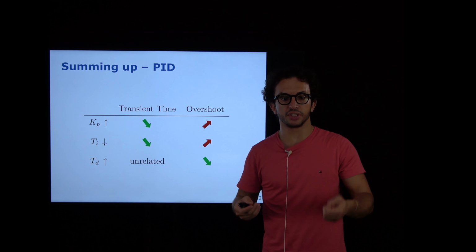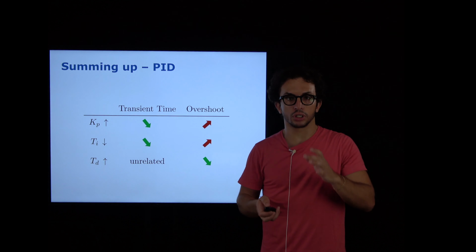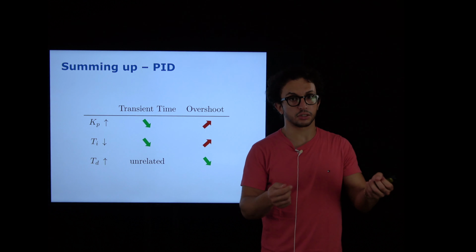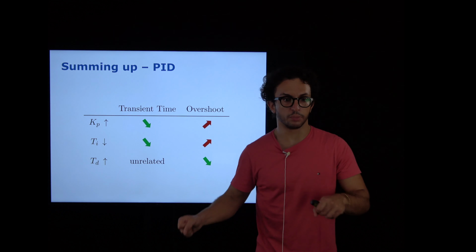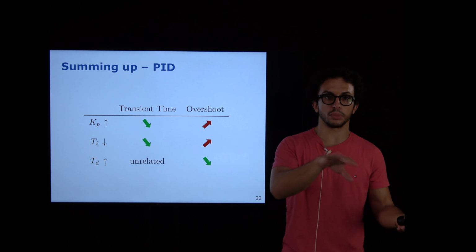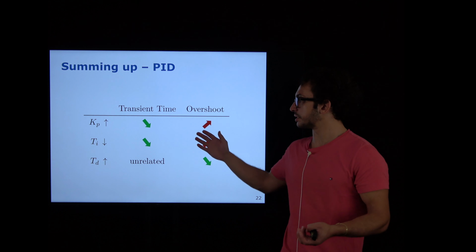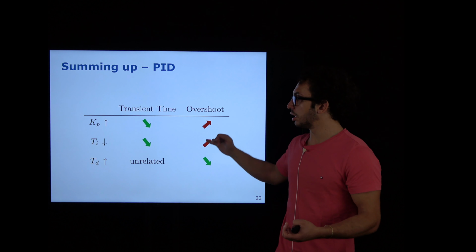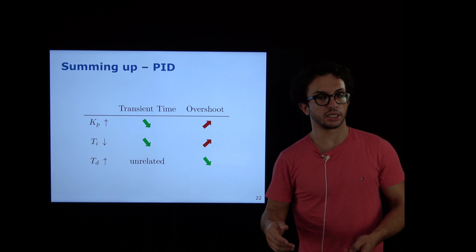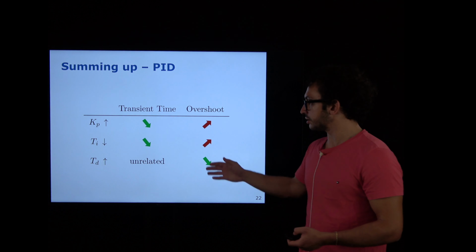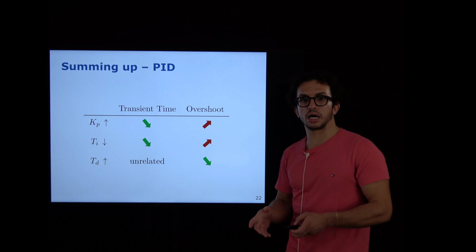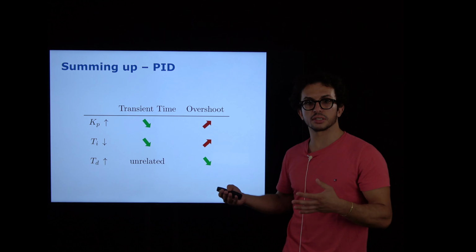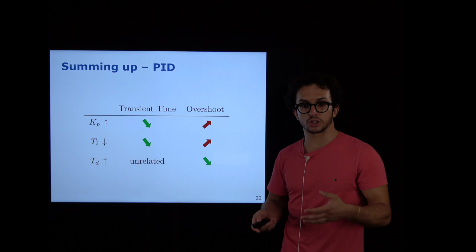And we said when we use a very high gain in the proportional term, the system actually can oscillate a lot. It's faster for sure, but it oscillates. And again, with the bicycle, it might cause oscillation, and then might also cause instability. Oscillations are also present when using an integral gain, but again, the derivative term, remember, acts as a brake. So it's something that brakes the system, and therefore the overshoot is actually reduced.